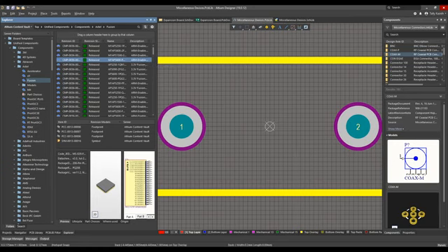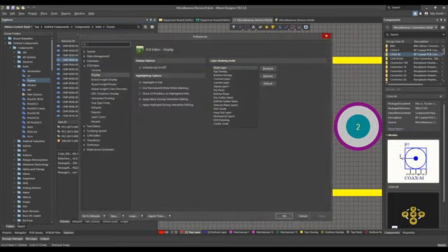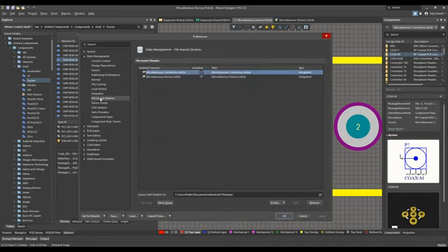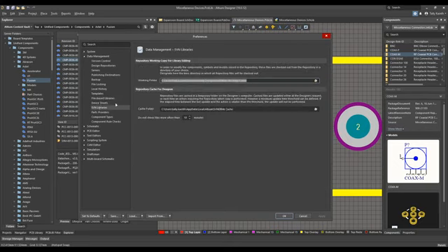Altium supports another type of library called a database library. There are a few types of database libraries: dblink, dblib, and svndblib. The dblink library provides an efficient means of linking and keeping the components used in your design synchronized with the data entered in the database. The dblib and svndblib approach takes this proven linking efficiency and adds the freedom to be able to place a component directly from the database. In essence, it creates the component directly from the information stored in the corresponding database record.